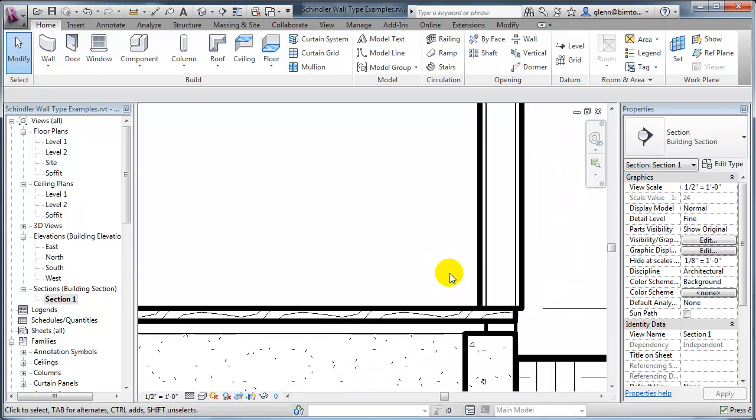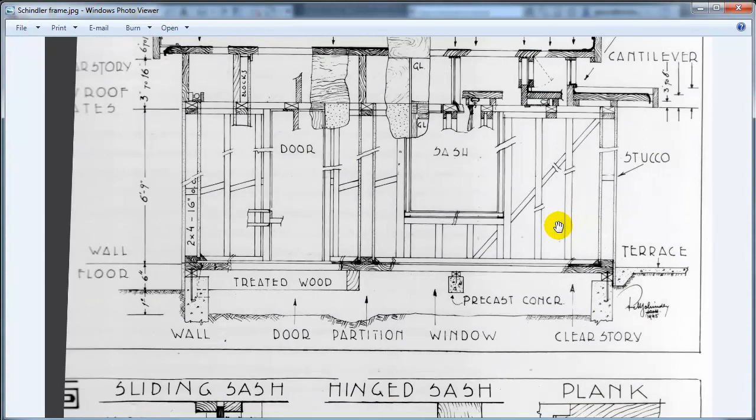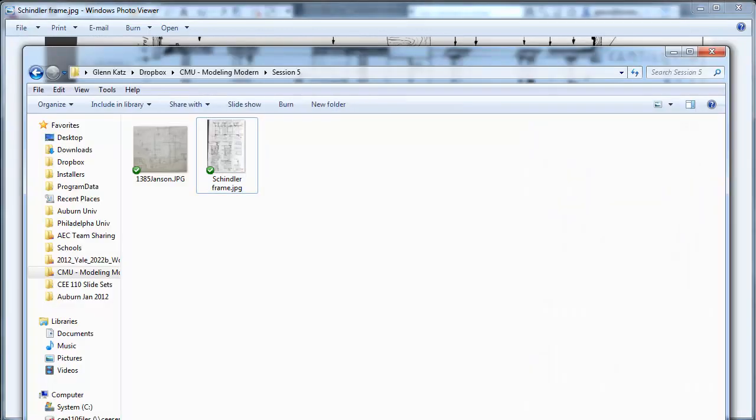We're actually placing the studs right at the face there. Okay, and that's what I really want to have happen. That's really the matching detail over there. The studs line up, not the actual finished layer of the stucco. So going through and just placing the exterior one, that's actually pretty good. We can set the heights as necessary. That one's actually already set to the 6'10.5", hopefully.